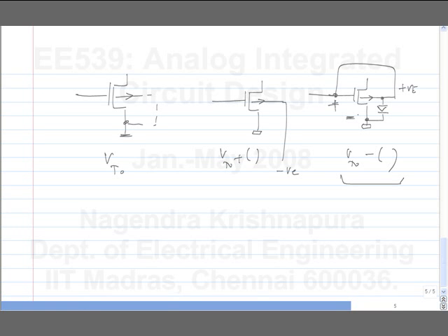That is because of leakage. If the leakage is insignificant, that's not true, right? See, the characteristic of the diode is exponential. So if you are operating somewhere here, it may be okay. If you are operating here, it's not okay. But whenever you do this, you always have a risk of forward bias. You can use it only when you know for sure that you will not forward bias it.